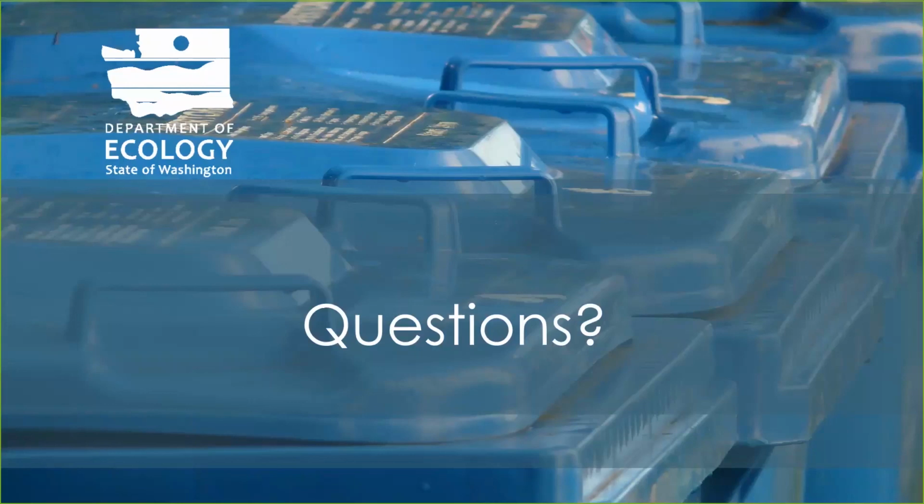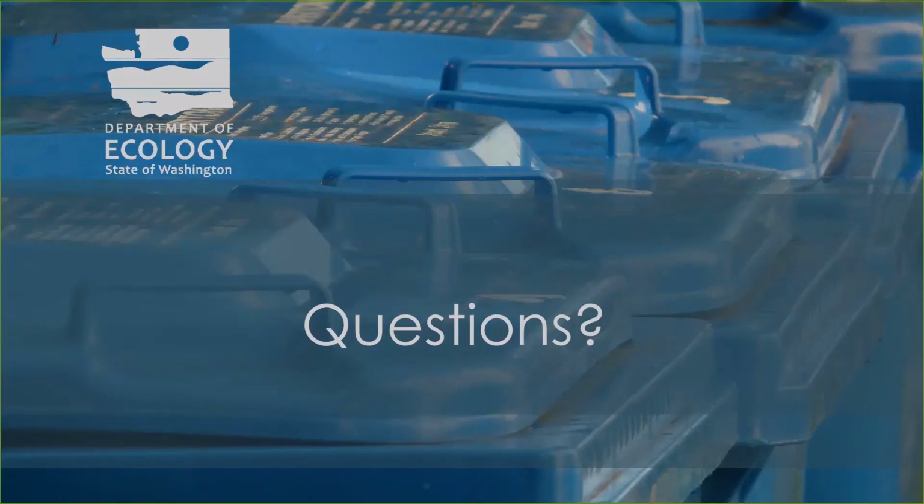And Bill will talk about that later. It doesn't require a specific liner system, so it's possible to have a limited purpose landfill where on-site soils can be shown to be protective, and groundwater monitoring might not be needed depending on what your acceptance criteria is. So it really just depends on the kinds of materials you would plan to receive.